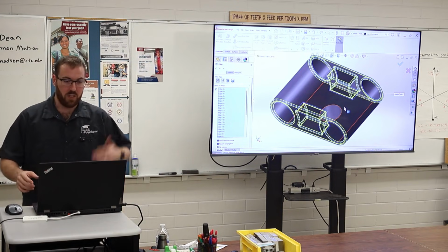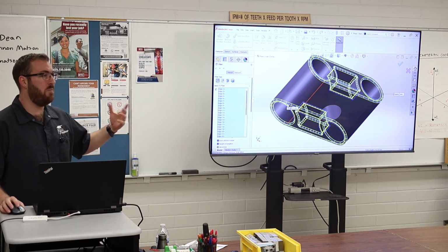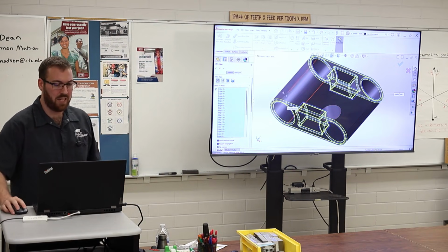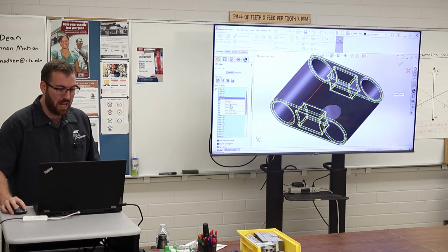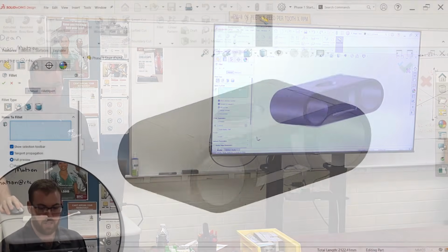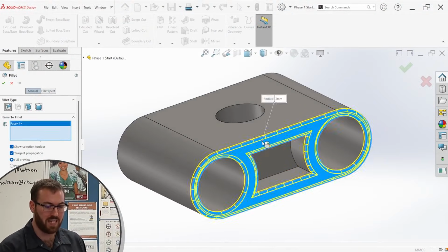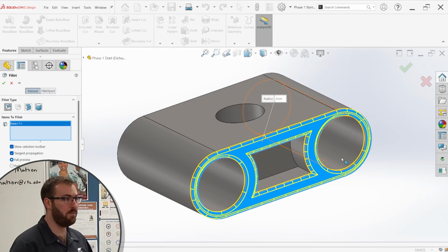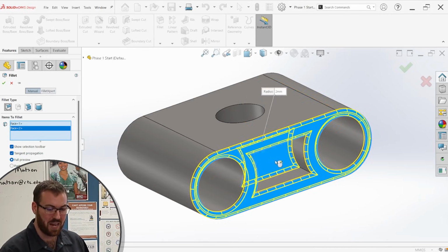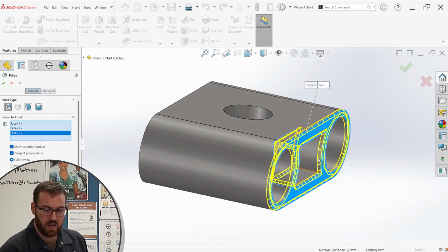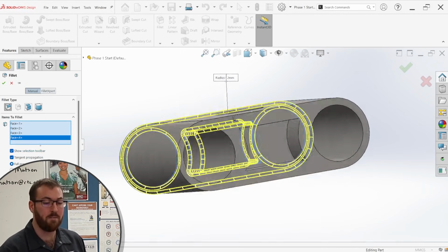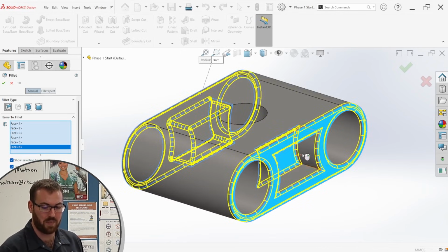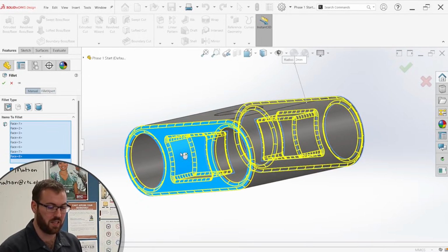Now, one other recommendation, because there may be situations where you have more than 2 edges you would have to deselect here. If you do have to manually select for fillets, use faces. That's my recommendation, because faces will include all the edges associated with that face, and it's just easier to pick them. And it's more difficult, I should say, to forget something. So I can get an equivalent result by selecting those faces, right, if all else fails.